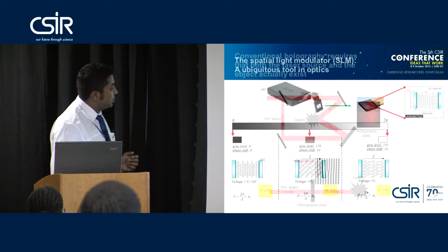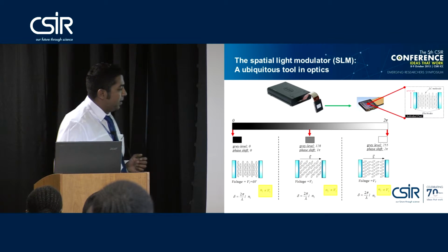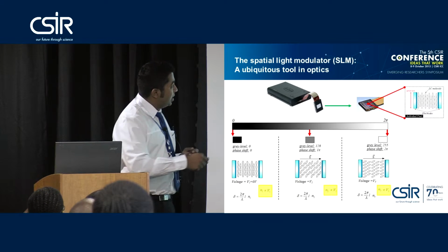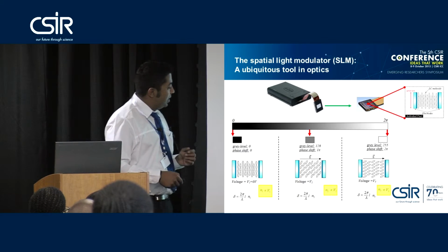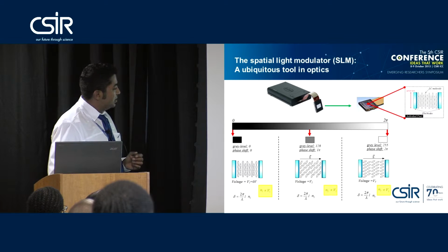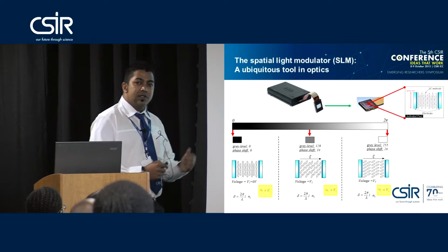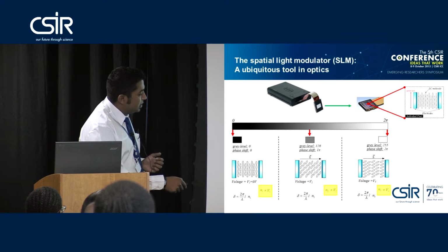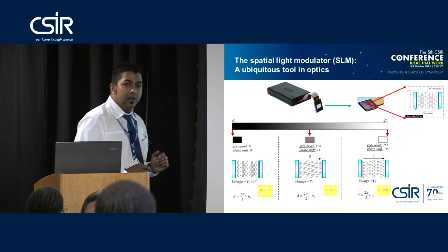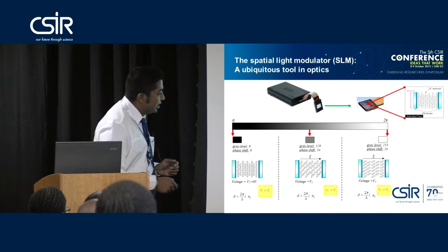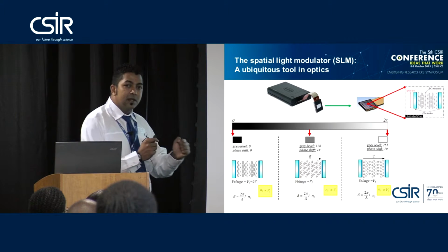And we use a device called a spatial light modulator, where our digital holograms are addressed onto a little screen here that's made up of liquid crystals. And as we apply a voltage across the screen, the molecules in the liquid crystals will start to bend. And as they bend, if I send light through them, it will be refracted a little bit.